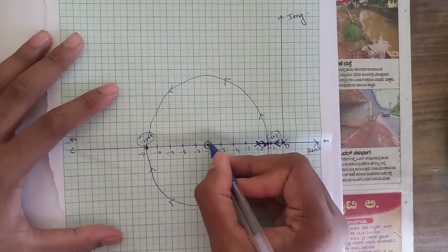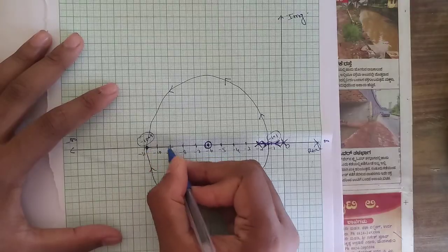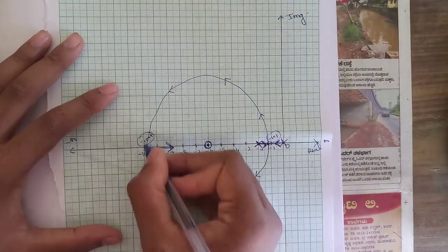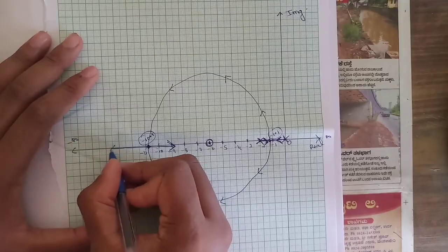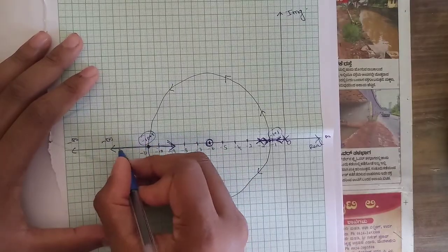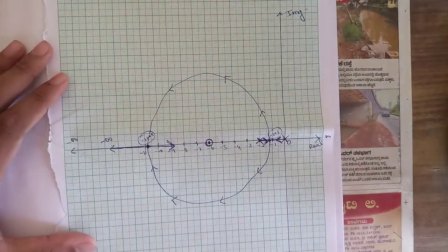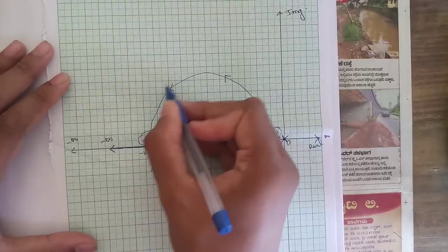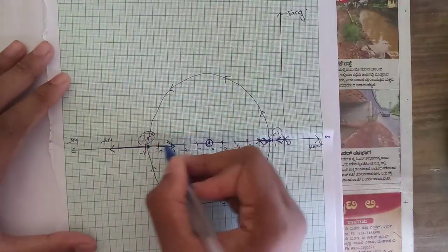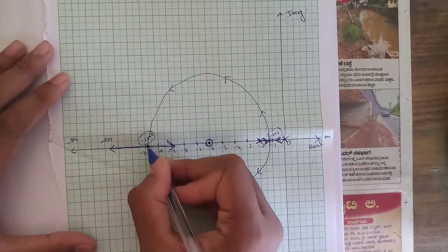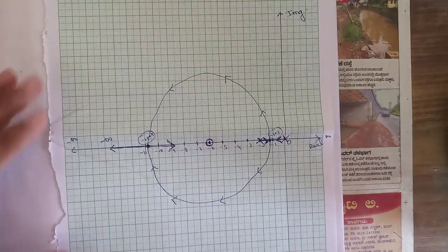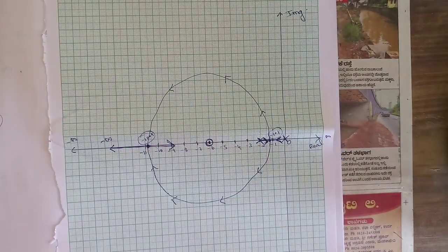So now we know that since we have one zero, one of the branches would be approaching towards the zero and terminating at the zero, and one of the branches would be approaching towards infinity, because we have one angle of asymptote that is 180 degrees. So that's why it would be approaching towards that direction only. That's why one branch, either this branch or this branch, would be approaching the zero, and from this point the other branch would be approaching towards infinity. Okay, so this is the root locus plot obtained, and the condition they have given is that we need to get part of the root locus as a circle, right?